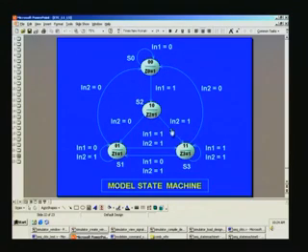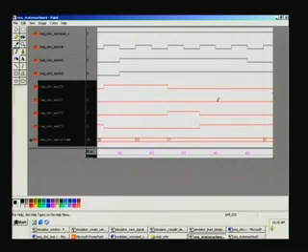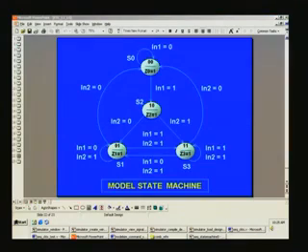So, we were in this, right. So, 0 1 would take you to S1 state. So, that is it. This one, the 0 1 here, right, and I hope you have kept track of all the LEDs for Z0 through Z3. In fact, I forgot to mention, but you can verify one of them here. So, for 1 0 state, same thing you should get here, Z2 must go. So, 1 0 is 2, so Z2 must go high. So, this verifies at random, and finally we have one more waveform in the state machine.